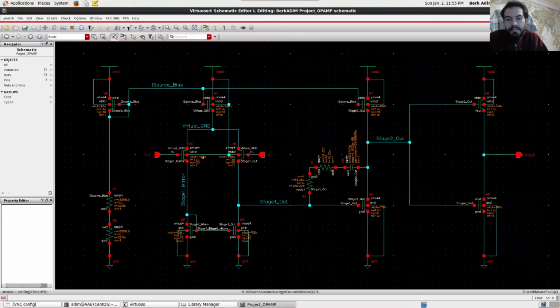But we are using a PMOS input stage because we want our DAC output to accept common mode inputs as low as 0, and while it cannot accept as high as the supply voltage, it actually can accept 4 volts. We are using a 5 volt supply here. It can work in 4 volts, so we actually have a wide input common mode range.